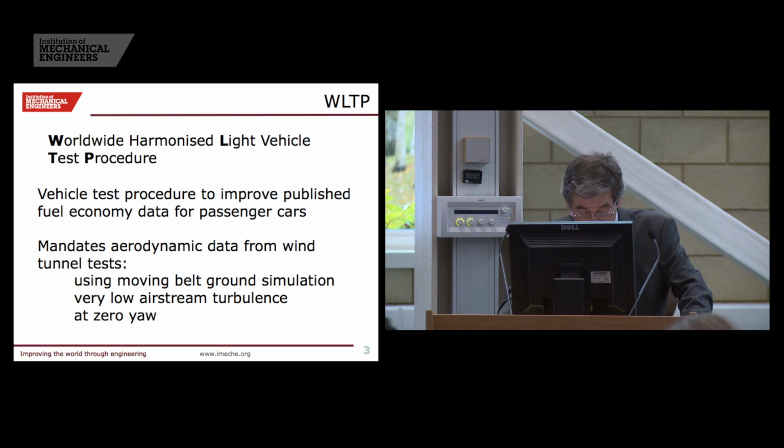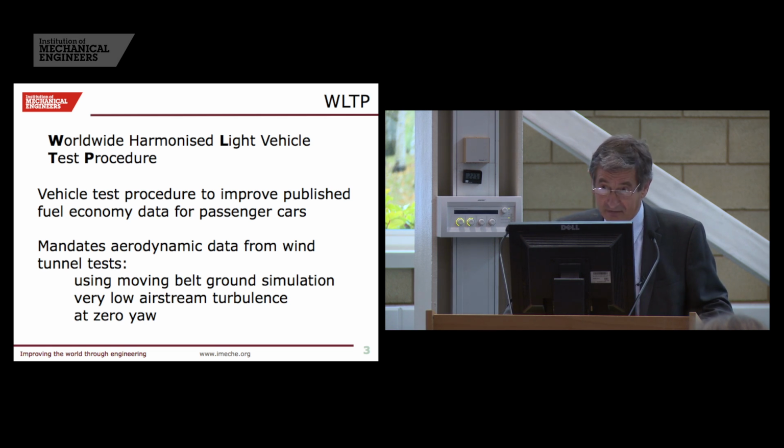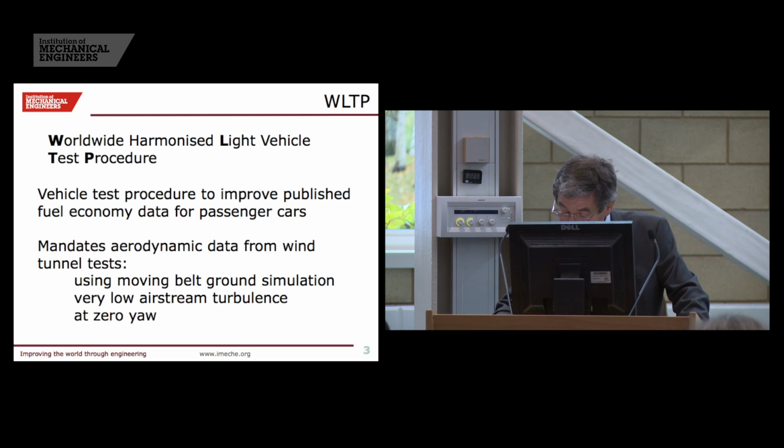It mandates in the wind tunnel testing that is part of that test procedure that moving belt ground simulation must be employed, but it also says it's got to be in very low airstream turbulence, and it's also only identifying the drag at zero yaw.